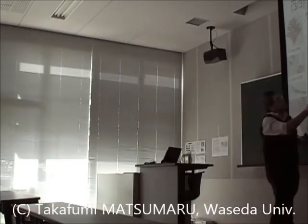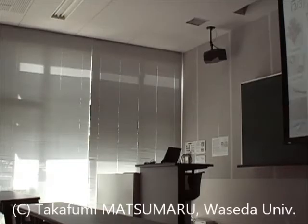This is also used in the Shinkansen's pantograph to capture the electric energy. This is an electric line, and by sliding along this part, the electric energy is given to the car body. And here the vortex generator is put on this part to reduce noise; the vortex generator reduces wind noise.